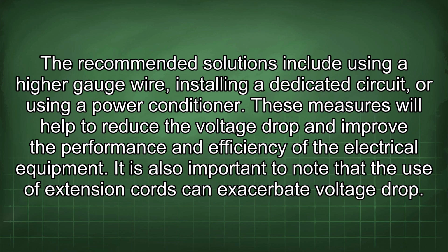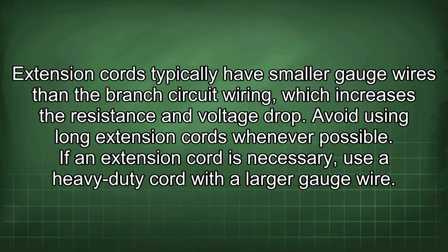It is also important to note that the use of extension cords can exacerbate voltage drop. Extension cords typically have smaller gauge wires than the branch circuit wiring, which increases the resistance and voltage drop. Avoid using long extension cords whenever possible. If an extension cord is necessary, use a heavy-duty cord with a larger gauge wire.